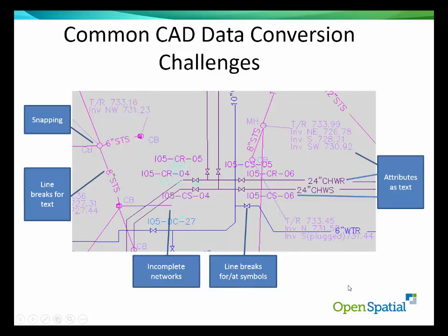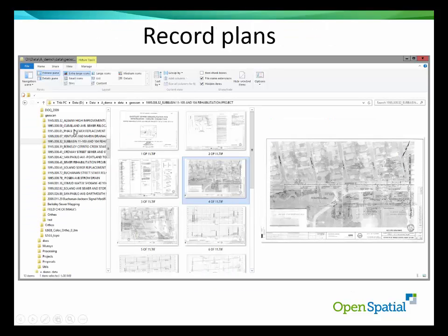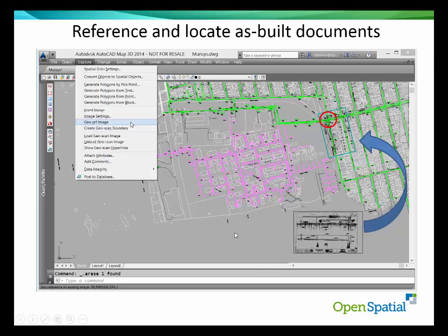So let's just look, for example, at this. Next step, a lot of paper information scanned. Here's a set of folders with projects in them, and each of the projects may be one PDF or individual TIFF files. Let me show you what we do with those. We take, say, this plan view here, and we literally pull it into the map by using the Munsys features. This is Munsys on top of AutoCAD. You can see the menu here is a Munsys menu, whereas the environment is CAD. So, an application in CAD. Here is insert the image, that'll put it there. And then you can use the geo reference image tool, which says give me 2 points on this image and locate them where that box is, so that now you've put it in its place.